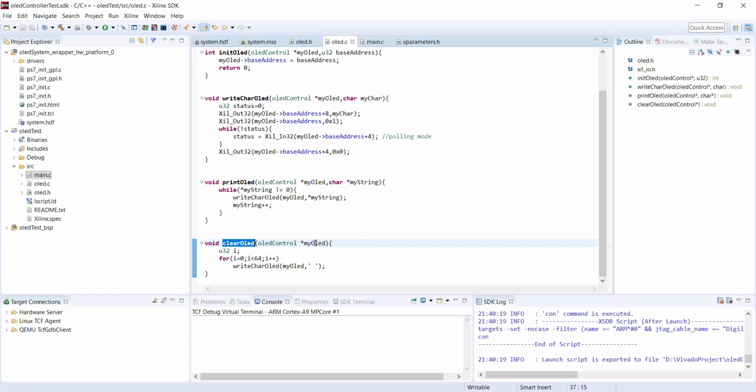You can have additional registers where you can specify the page number and the column position, and your state machine takes the page address and the column position from those registers. Currently we don't have such control; it simply increments each time we send some data. Instead, it takes data from these registers to decide from which position to display, so that you have better control.